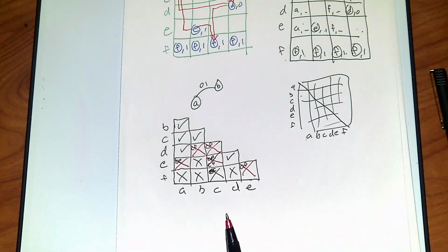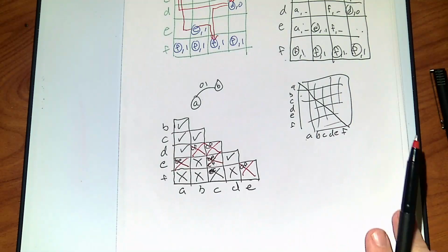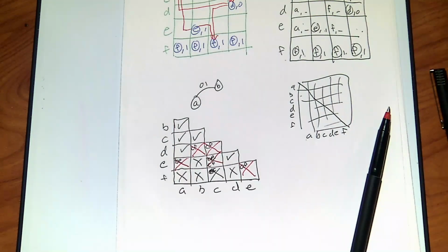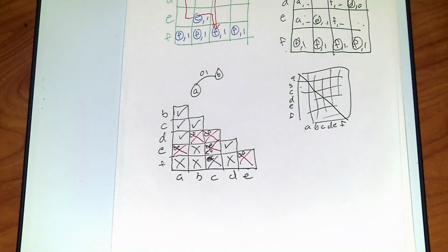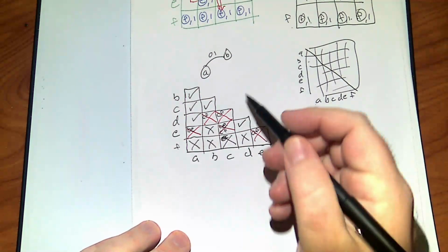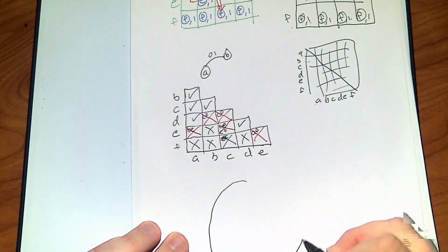Now, if you looked at this chart, we're now done. Can I just merge all of these states? Anybody who's a check mark, I merge them? No. So now the question is, how do I? This is pairwise compatibility. It's not complete compatibility. So what I find to be helpful, and this is another one of those neat graph things, is to turn this into a compatibility graph.